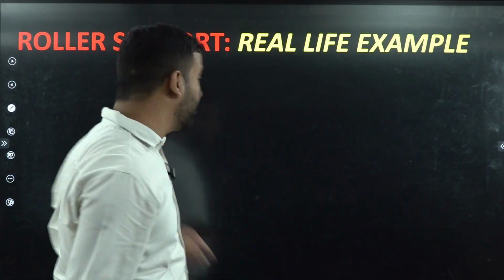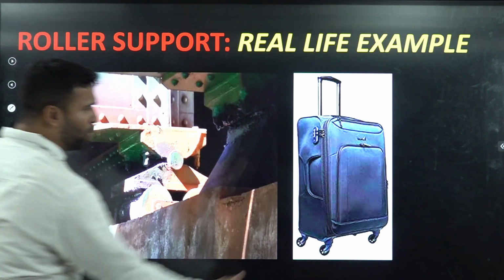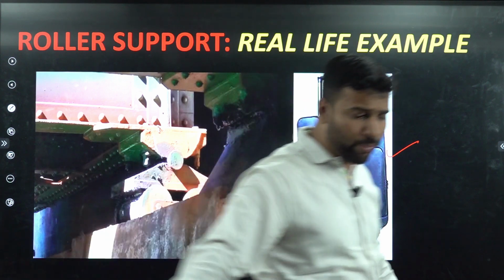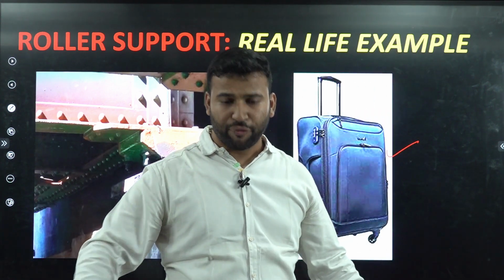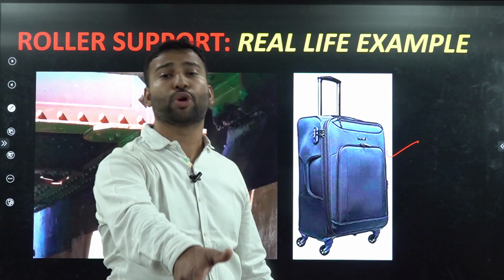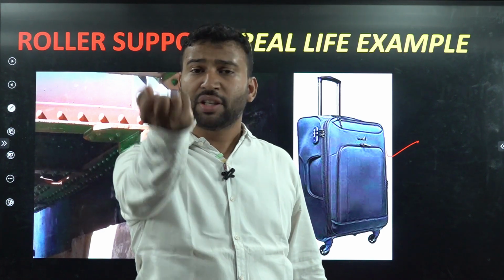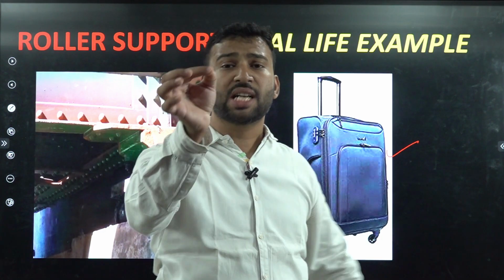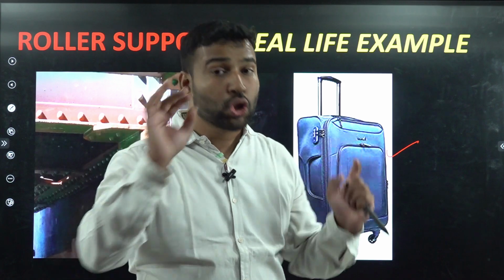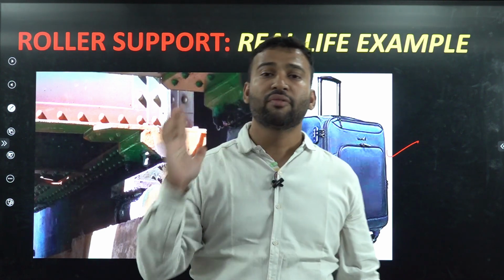Now we will see some real life examples of support. This is the real life example of roller support, students. If we look at a trolley bag, it will have roller support here which will allow the horizontal movement of that particular trolley bag very easily. If we try to rotate that trolley bag in the circular direction, it will easily rotate because rotation is allowed, horizontal movement is allowed. Now if you lift that particular briefcase in the upward direction, there always exists a downward reaction which will try to bring that briefcase in the downward direction. So on every roller support we have only one vertical reaction, that is only in the vertical direction.